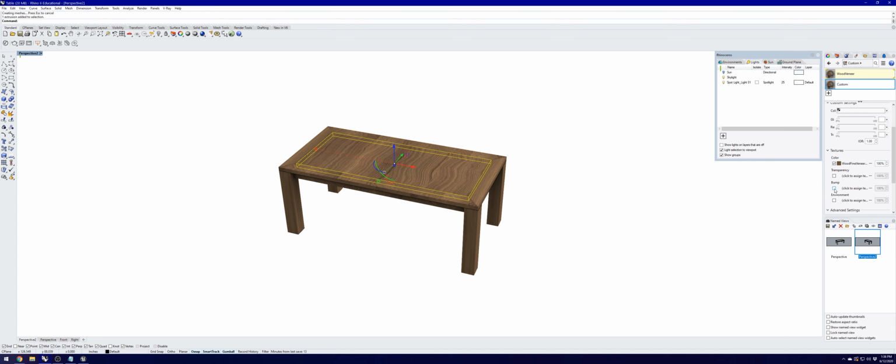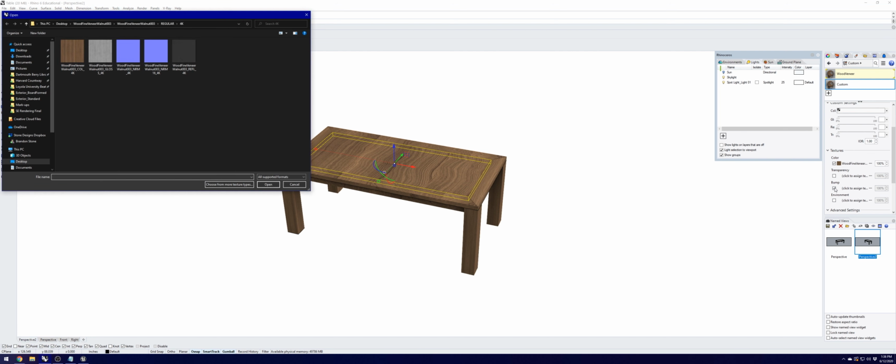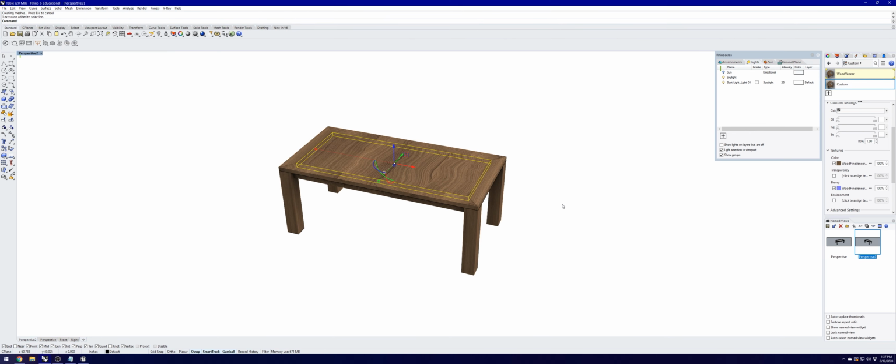And then I'm going to import both our color, or what's called the diffuse map, and my bump map, which will be converted automatically into a normals map within Unreal Engine. So when I click the plus next to bump, select my bump map, which is also considered a normal map, hit OK. You can't see anything changed in that little thumbnail, but it basically just adds a little bumpiness or little texture grain, I guess you could say, over the top of your otherwise flat static diffuse texture.